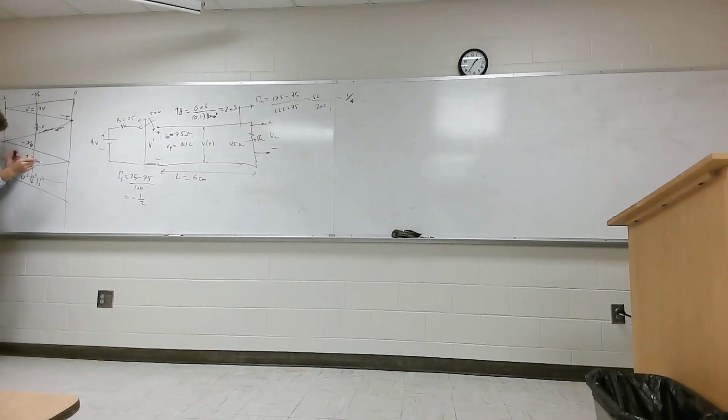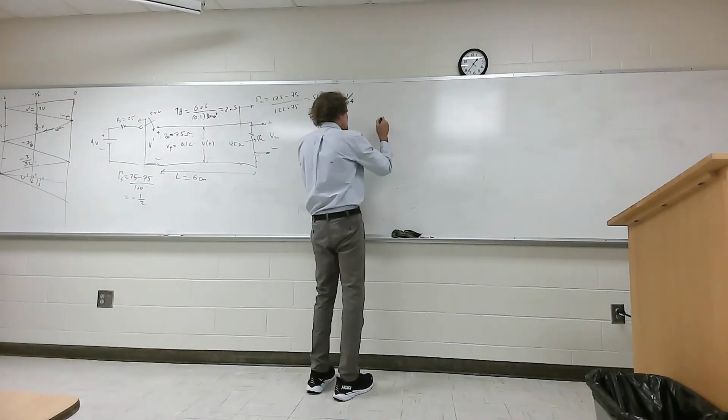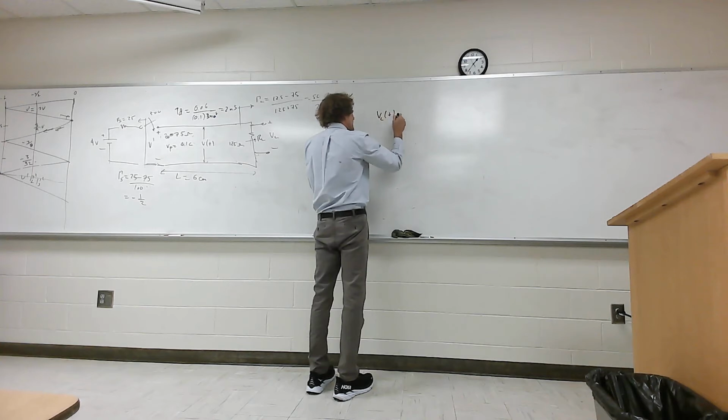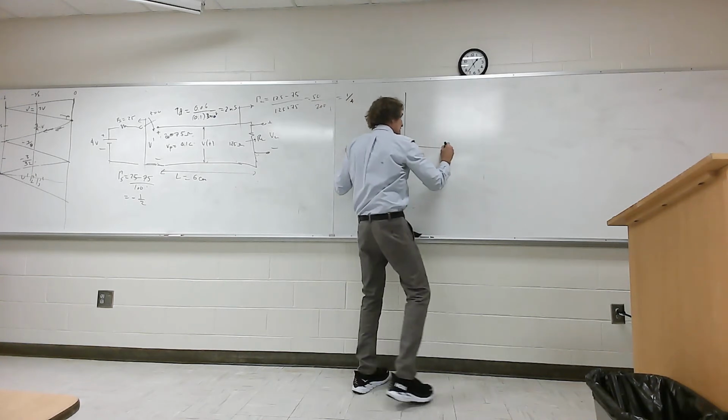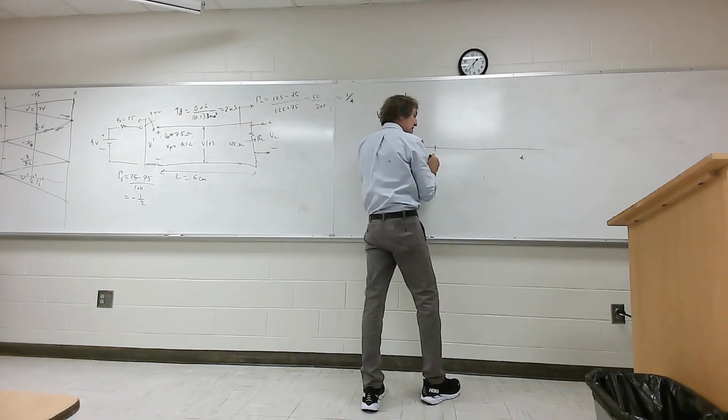Right? If you think about it, you could get the transmission coefficient, which is 1 plus the reflection coefficient, and multiply that times the actual incoming wave, and you'll get it. But I like to say it's just the simultaneous addition of these 2 things because they're concurrent. They happen at the same time. So if we do the voltage at the load versus time, basically nothing happens until I go 2 nanoseconds, because that's the time delay.